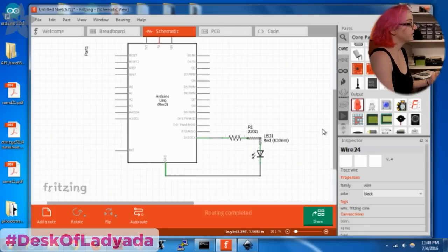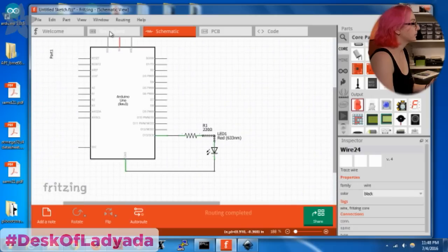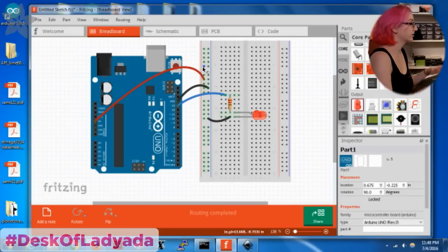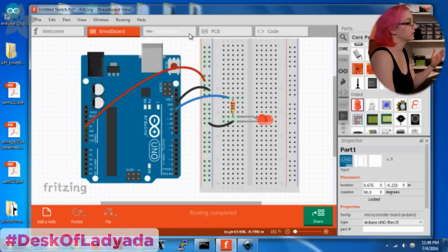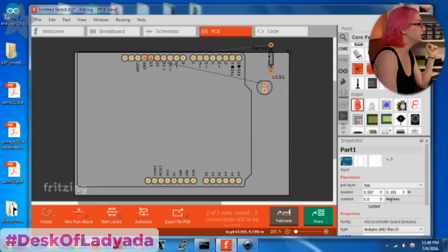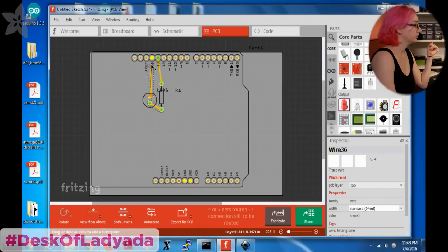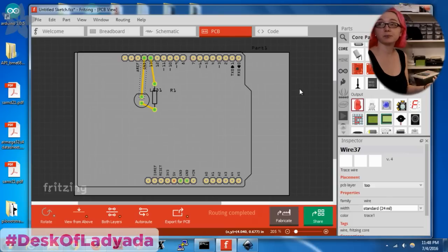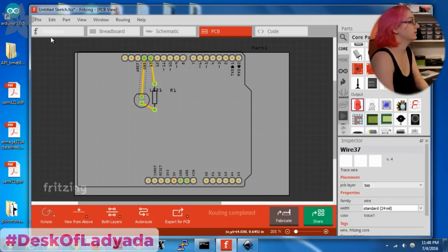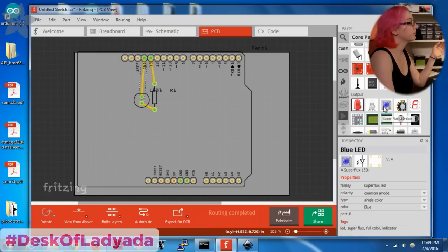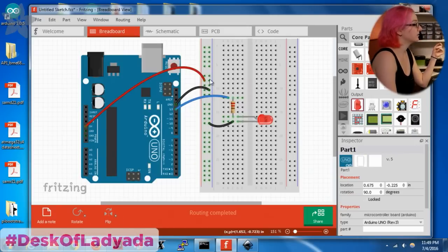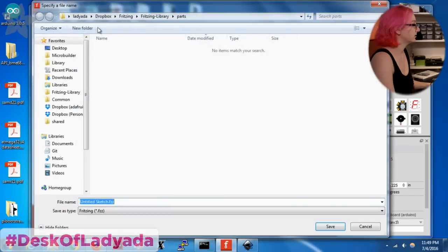I mean, it's a very basic schematic editor, but what's neat is the breadboard view and the schematic editor are tied together. So if you draft it on the breadboard, it shows up as schematic and then as a PCB as well. So if you want to make a custom shield, you can do this and route copper with just lines. It's very simple, but it's very effective. It's a lot easier than EagleCAD for people who really just are like, look, I want to get the 4 LEDs on a shield and a button. And if all of those parts are in Fritzing, it's very easy.